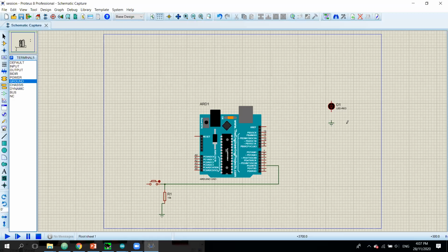Connect this one, and then I'm going to connect this pin to pin number 3. So here you need to add the power source. That means you need to apply 5 volt from this board, or some outside power source. You can prepare a power supply module or something to power these buttons and the Arduino board.